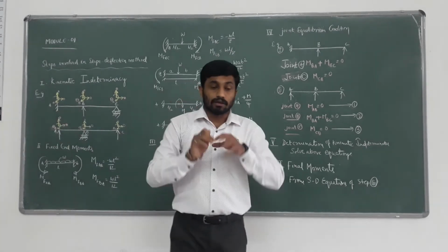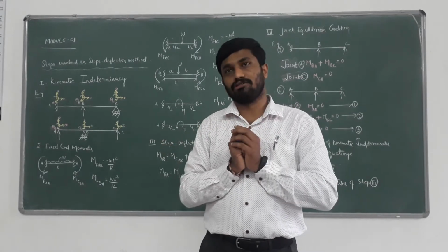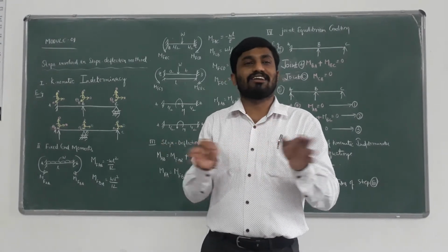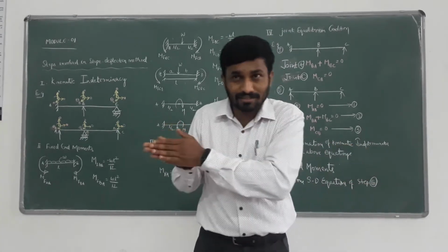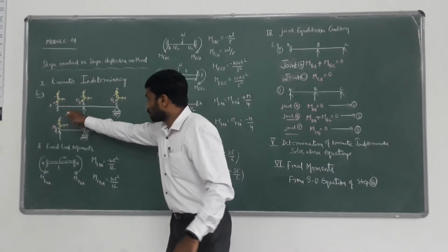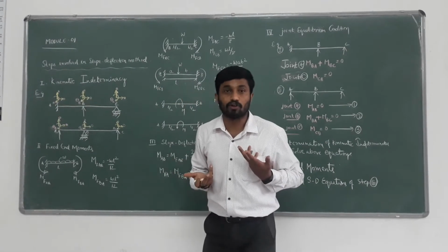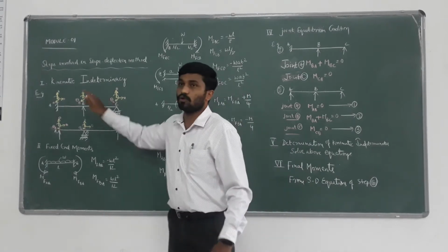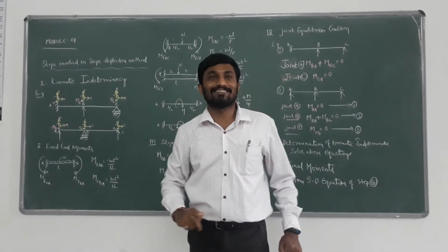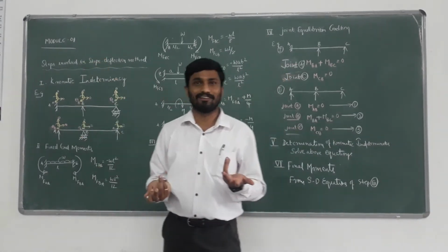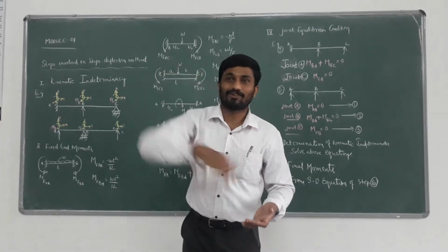Also, our assumption in solving indeterminate structures is axially rigid, which means there are no axial displacements. So in the x-axis, because of this fixity, or if I assume axially rigid, the horizontal displacement is 0, not allowed. The only possible one is rotation. Here there is no reaction to resist the rotation.